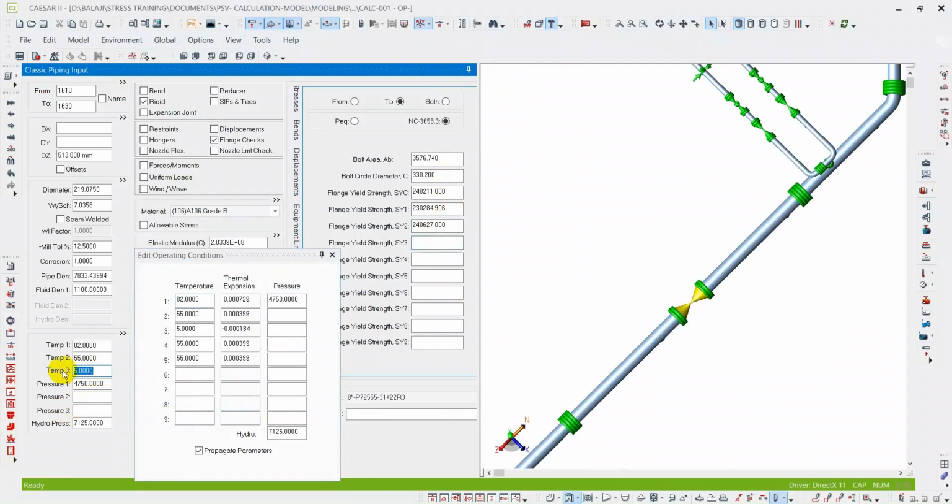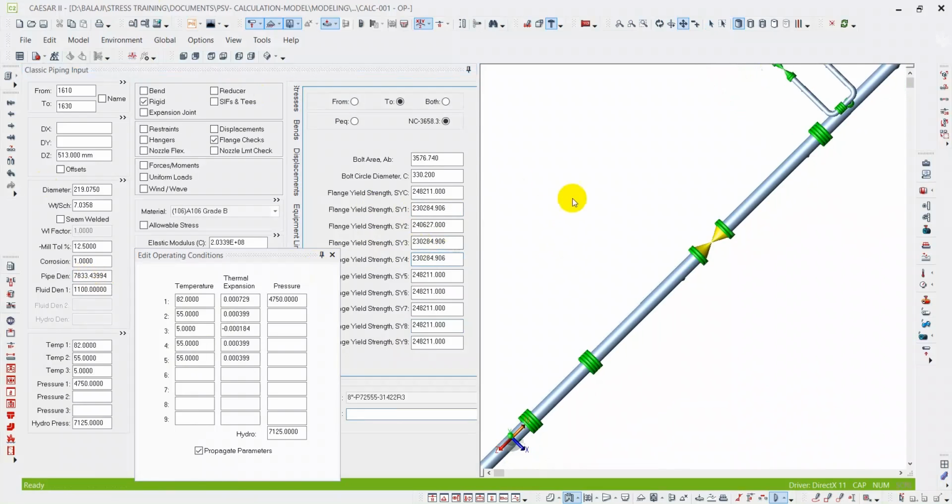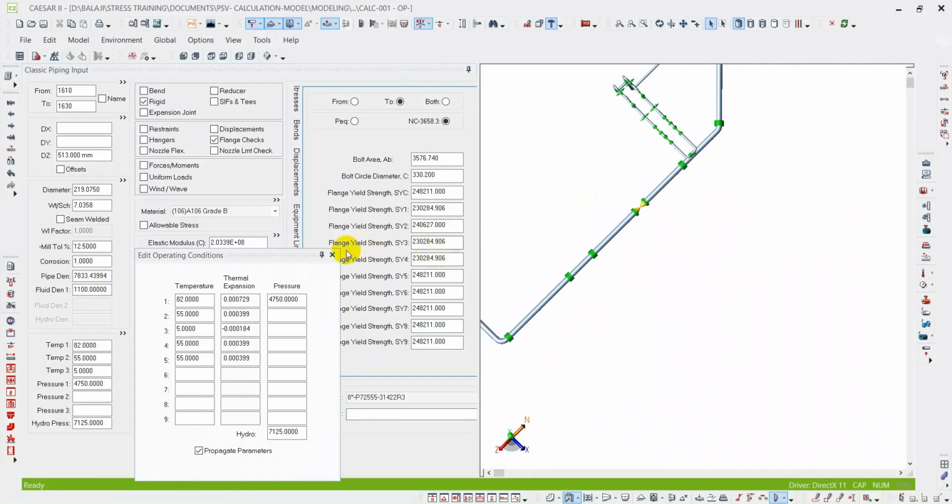So this comes under 5 degree, that means it is within 100 degree Fahrenheit only. So you can take the value from here, or you enter all the values like this. You have to enter the correct yield strength value based on the temperature. So T4 and T5 is this value. We can select T4, T5, this one. Like this you have to do the analysis.